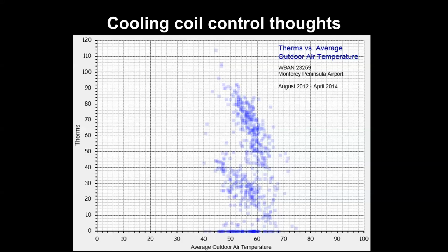As an example of what we mean by that, let's take a look at this chart where we have average outdoor air condition plotted against natural gas usage at a specific building. So what is this data telling us? Well, one of the things that you might notice is that there's these two patterns that emerge here. And if I told you that this was for a building that only used natural gas for space heating, that might be confusing, because you would expect, if this was filtered for occupied hours, as we did, that as it gets colder, there'd be a single pattern where your natural gas use would increase.